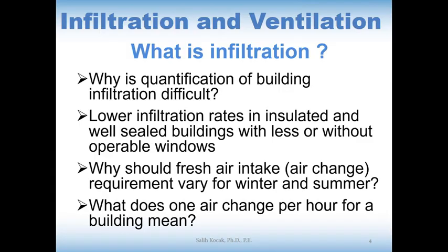We just said it in the previous bullet. Because in winter there's wind and there's a huge temperature difference in and out. That's why it is 50% more than summer. So summer 1 is okay. If nothing is given to you, you have to take the summer as 1, and the winter 50% more of 1, which is 1.5. And you gotta divide everything by 60, because 60 minutes per hour.